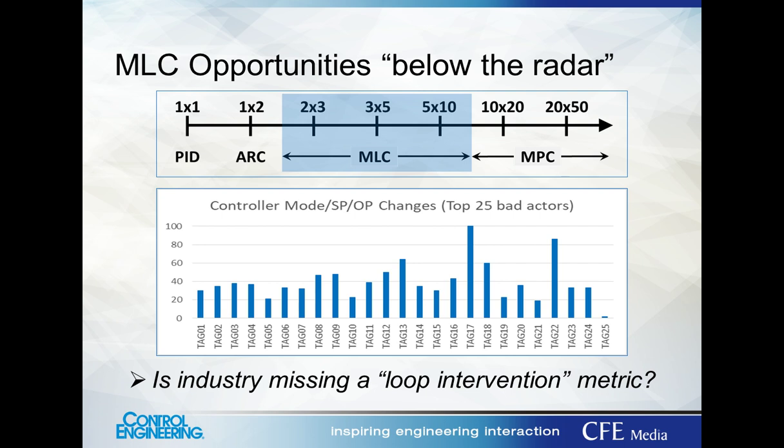It's a fair assumption that many or most of these represent manual multivariable control scenarios where operation becomes caught up in frequent micromanagement of groups of related controllers. I think we've all seen that. Moreover, every single intervention represents lost opportunity that had an automatic multi-loop controller been deployed, the moves could have been made in a more timely manner, capturing greater optimization. Not to mention allowing the operator to play a more process oversight role by relieving them of this repetitive task.